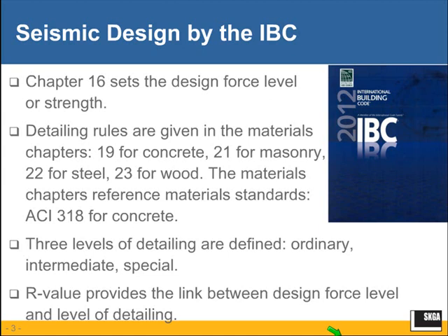And then the R value, which is also in Chapter 16, provides the link between the design force level and the detailing rules in the materials chapter. As you know, the higher the R, the lower the design force level, and the higher the need for inelastic deformability or very careful detailing.